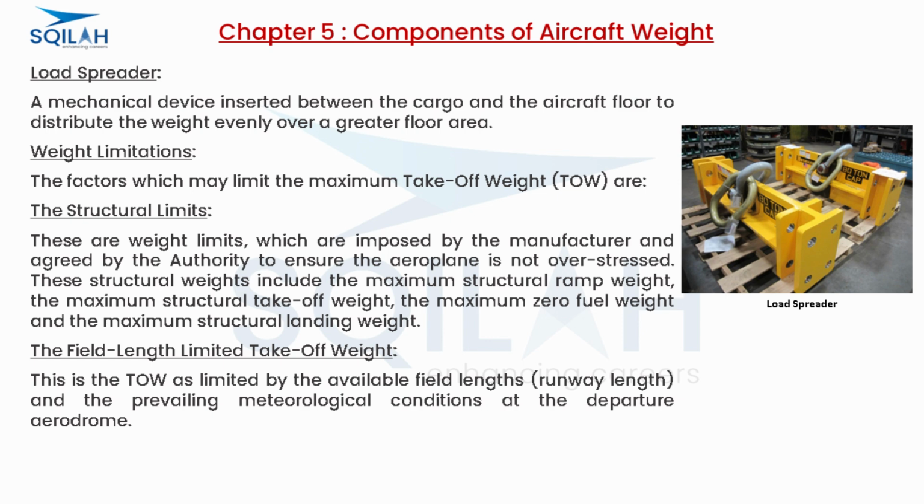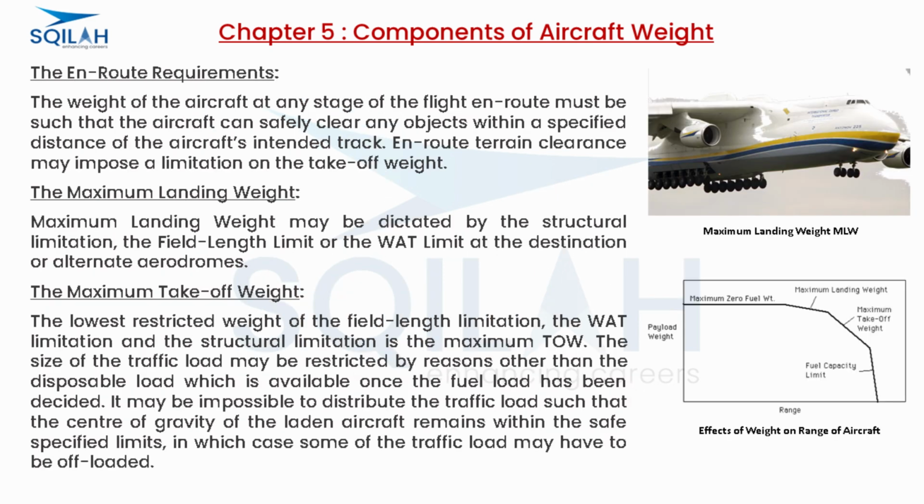The field length limited takeoff weight. This is the TOW as limited by the available field lengths, runway length, and the prevailing meteorological conditions at the departure aerodrome. The en route requirements. The weight of the aircraft at any stage of the flight en route must be such that the aircraft can safely clear any objects within a specified distance of the aircraft's intended track. En route terrain clearance may impose a limitation on the takeoff weight.